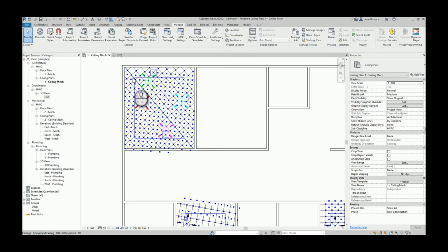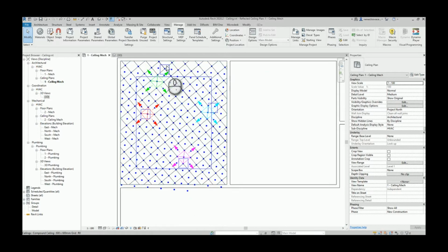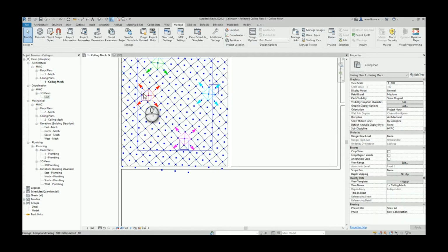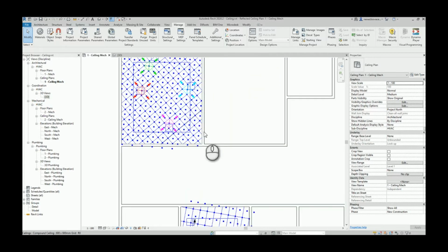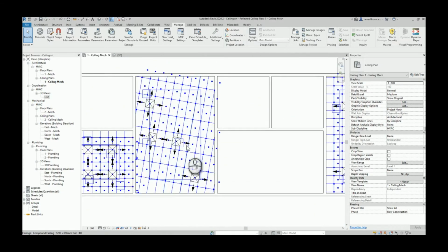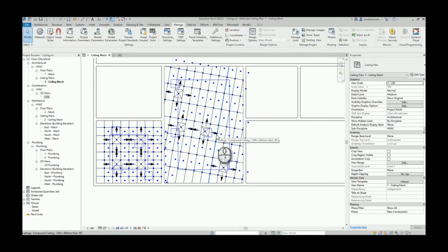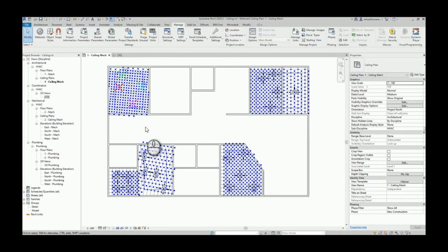So basically you can see that offset area over here, and you can see that this air terminal jumped from this location to this location, and you can see also that the previous position of the diffuser is now rotated. This diffuser is here. So basically every diffuser changed location, and if the diffuser also needed to rotate, it rotated now. And for a moment I will close the Dynamo so I can lose all those dots and lines, and it will be easier for you to see the new location of the air terminals.